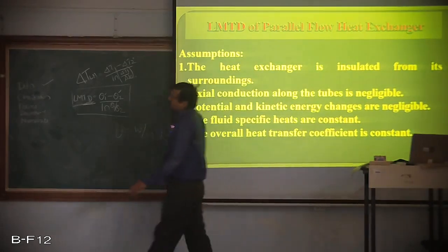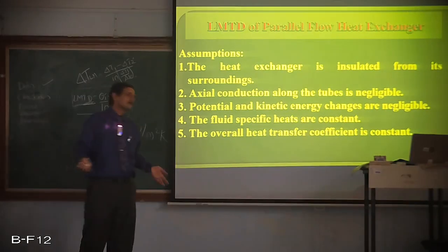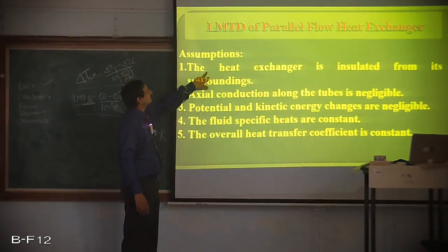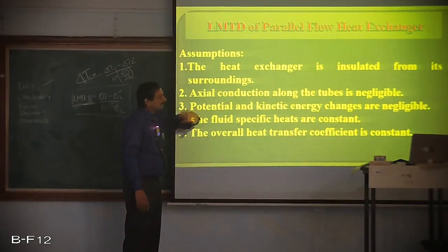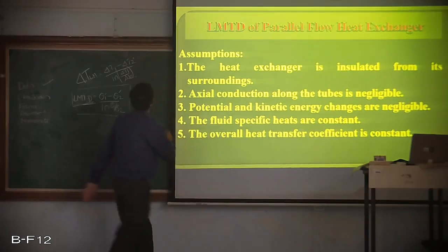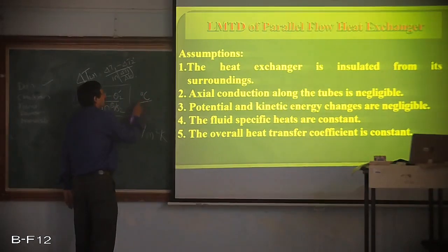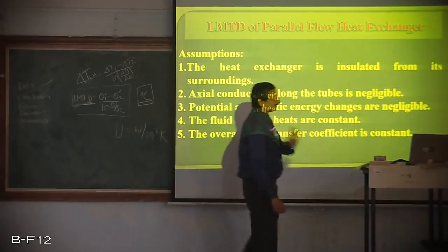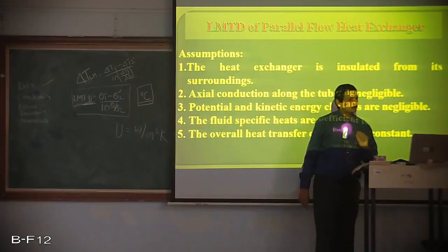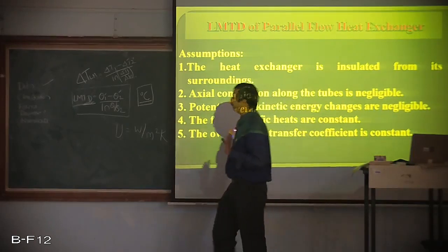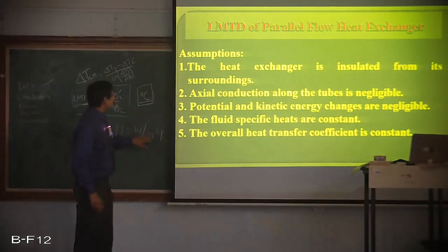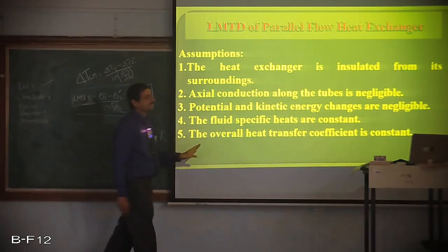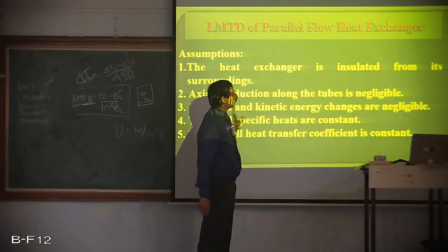The question comes, whether radiation is involved here. The answer is no. Radiation is not considered in any of this. The first assumption says that only. Hence, once radiation is not involved, you can use degree centigrade with confidence. You are free to use Kelvin also, but I will suggest you use only degree centigrade. Kelvin can be used; it hardly makes any difference to the answer. Please note this point very clearly.